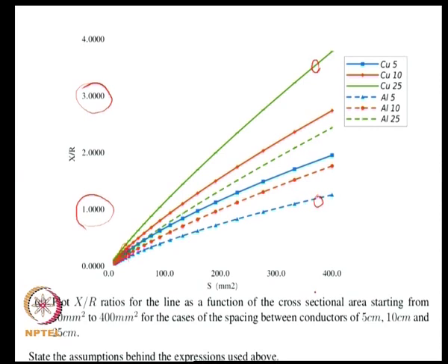We are also ignoring neighboring materials. You might have shields, you might have raceways through which you are passing your conductor, so we are ignoring packaging effects. We are ignoring stranding effects, as the conductors might itself be stranded. But it gives you a feel for what range to expect for your x by r ratio. Also, for the resistance we have considered the resistivity at 20 degrees centigrade. At higher temperatures the resistance would be higher.